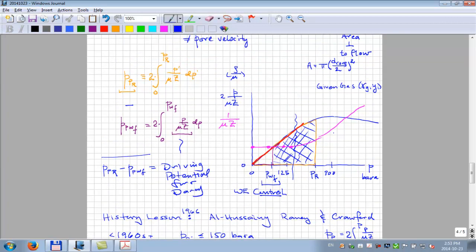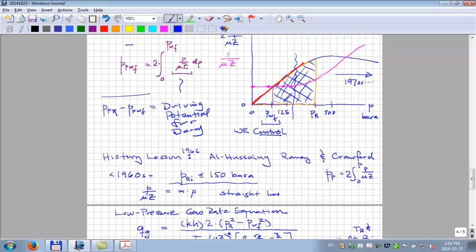You know, realize that most of that just kept getting, the initial pressure kept getting higher and higher and higher. They started drilling deep gas wells in Oklahoma in the 70s and it continues to today. All around the world, there's very little that is discovered that falls into this category of pressure squared low pressure assumption. So basically you have to use today the gas pseudo pressure method.